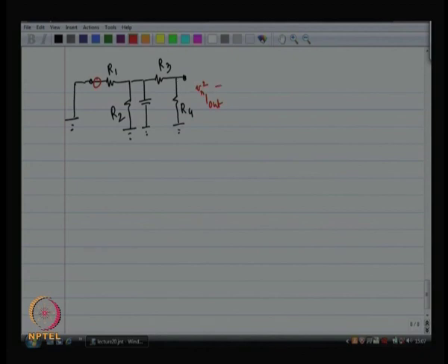Then do it for resistor number 2, then do it for resistor number 3, and finally do it for resistor number 4. And then you have to integrate all of these, presumably you have already got df inside your expressions. You have to integrate all of these over all frequencies. Okay. That will give you the total mean squared noise voltage over all frequencies.